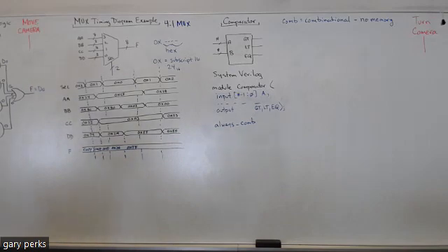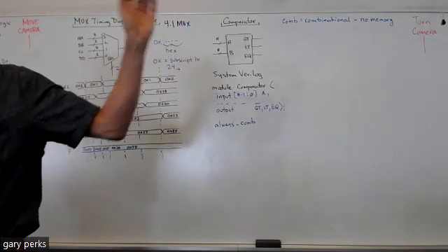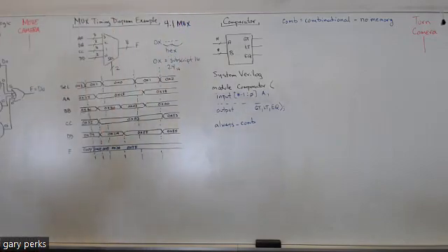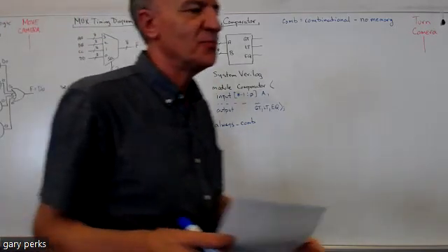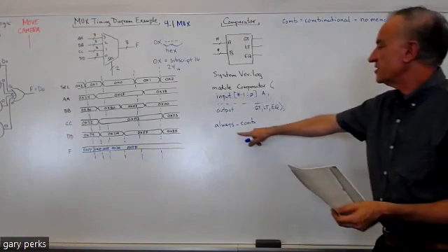And that's why, for the first 3 labs and the next couple of labs, if you get a warning with the word latch, I want you to treat it like an error. Because if in your Verilog design you have something creating a latch, that means it's creating memory. And we shouldn't be getting any memory because we're doing combinational circuits here. Anyway, I'll talk more about that when we get to sequential circuits in a couple of weeks.